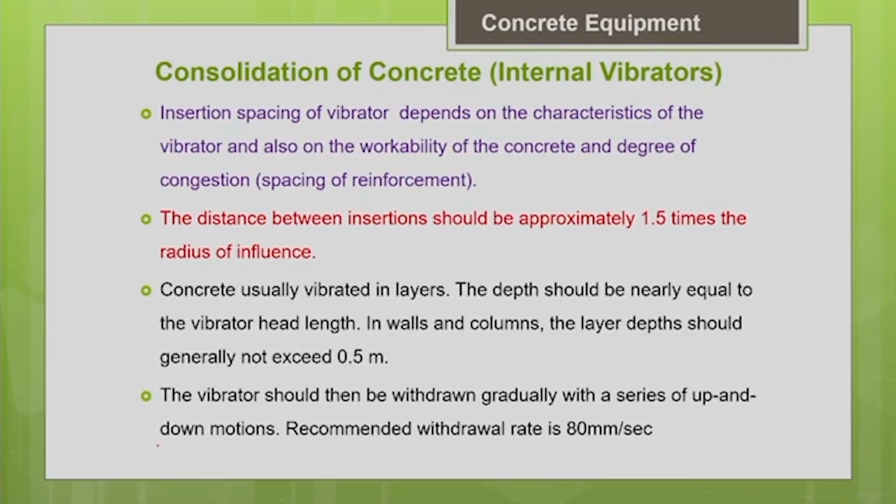If the worker who is doing the vibrating job feels that the concrete is very stiff, he will reduce the interval of spacing. When he feels that the concrete has better consistency, then he will increase the interval of spacing between the vibrators. That is how it is commonly done at the job site, just based on experience, by looking at the concrete consistency.